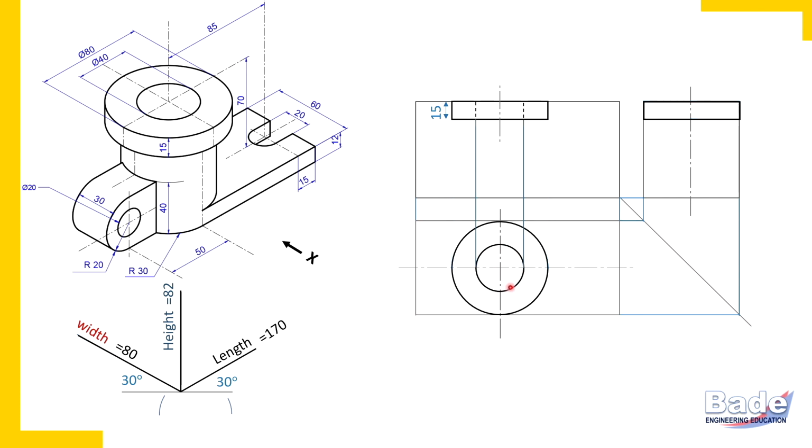Now I am projecting the hole, corresponding dotted lines. So where is this hole in the front view? Show me. So here it is. It is a rectangle and it is a dotted rectangle. Now transfer this hole in the side view also. In the side view also it is a dotted rectangle. So here is that hole in the side view. So have you realized, in top view circle, remaining two views rectangle. Using this simple logic we have drawn 3 views of this disk. Now let's proceed.